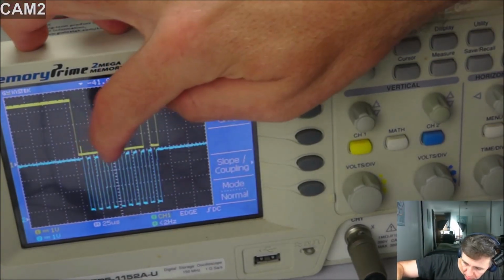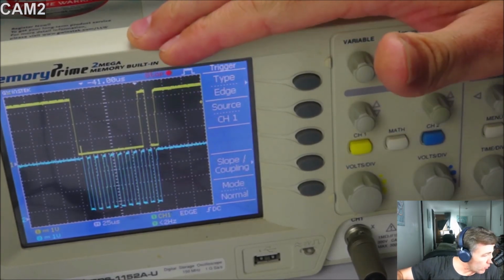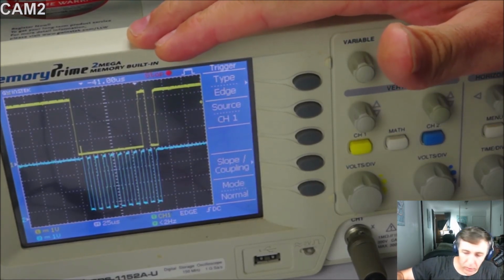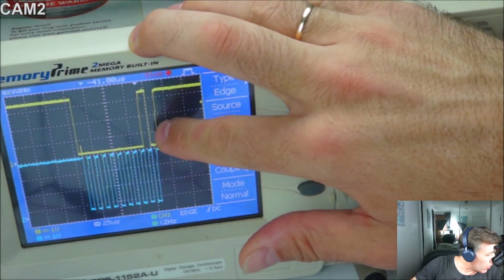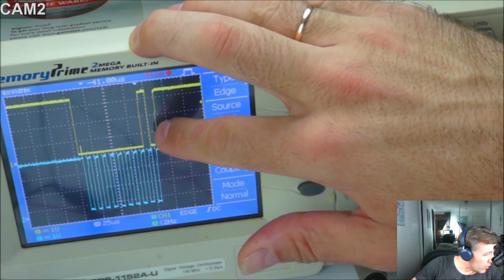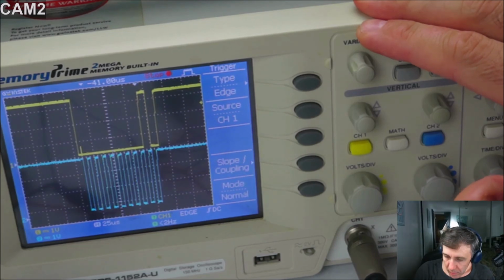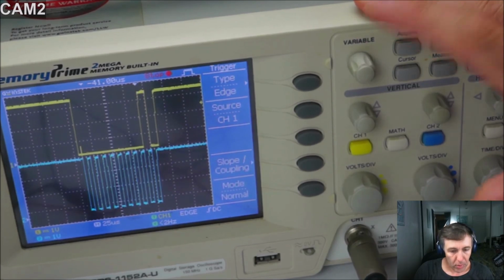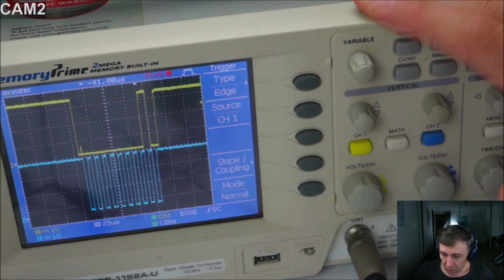It is 1, 2, 3, 4, 5, 6, 7, 8, 9 clock signals, 9 clock pulses. And this is the first byte. It doesn't look right, but at the very least, we can see those two signal lines toggling, which is good, which means that our AXI IIC core, the AXI IIC module, is functioning.